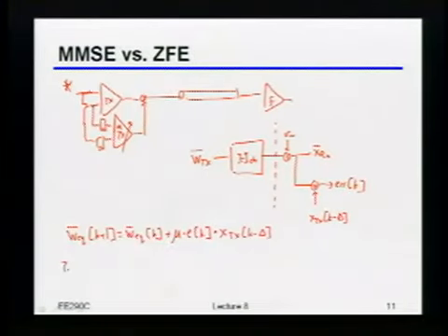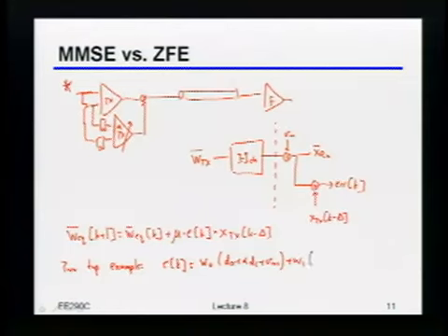You've convolved the channel with the transmitted data. Yeah, so inside of this error term, let's again do a two-tap example. That error term is going to be something like W0 times (D0 plus alpha D minus 1 plus Vn0) plus W1 times (D1 plus alpha D0 plus Vn1), minus D1. Okay. What am I multiplying this by, let's say, to update the first coefficient? Yeah, I'm going to be multiplying it by the vector D1, D0.